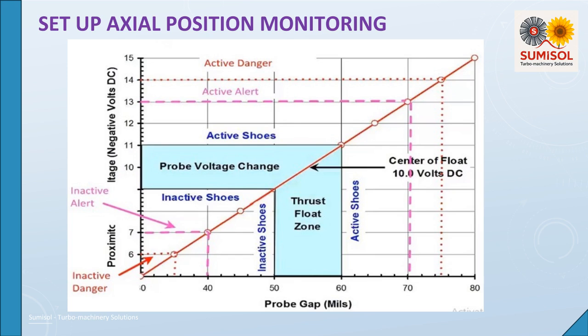The hot float zone will be more than the float measured in cold, with plus or minus 8 mils float. The hot float will be around ±12 mils. Set the alarm so that some babbitt will be removed before the alarm actuates, about 6 mils beyond hot float, or about ±18 mils. Danger or trip may be set 10 mils beyond alert, or at ±28 mils.